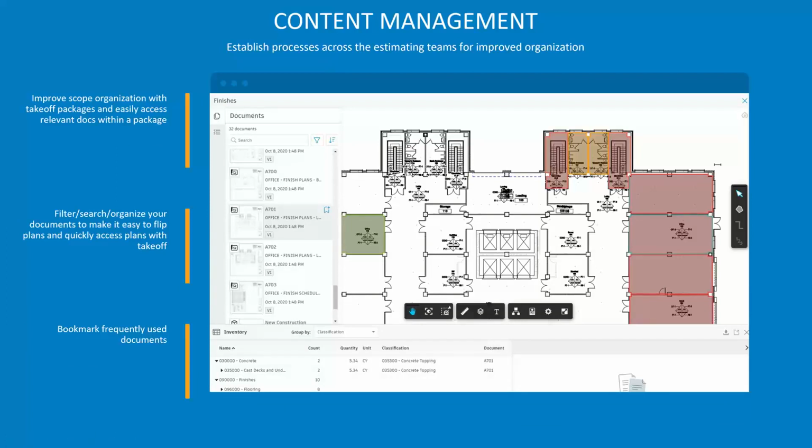So as I am sure Vincent was already talking about, Autodesk Takeoff is a quantification tool. So it's not a cost estimation tool here. It's a way of quantifying information both in 2D and 3D, and then tracking both either on 2D documents where you're literally drawing on the document and marking up and measuring the areas that you're taking takeoff of, or you're going into a 3D model and then you're actually picking the objects, and then it's giving you a lot of information about those objects, such as its length, its height, its volume, and it's going to give you far more accurate types of takeoff information.